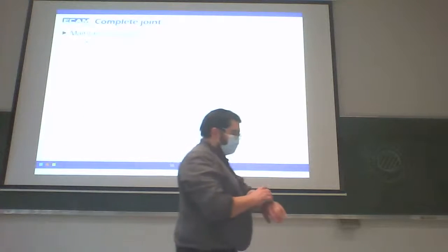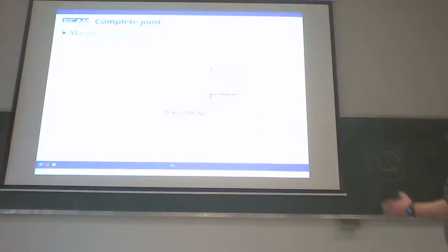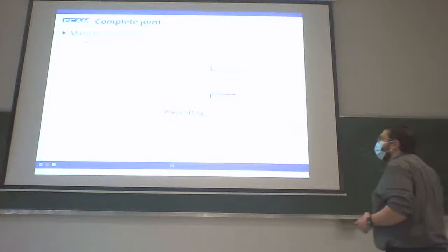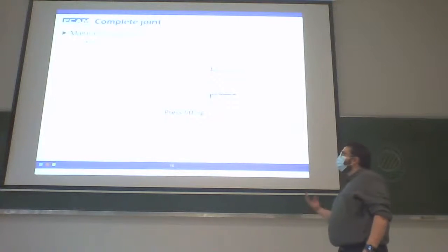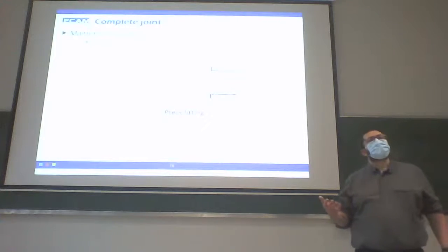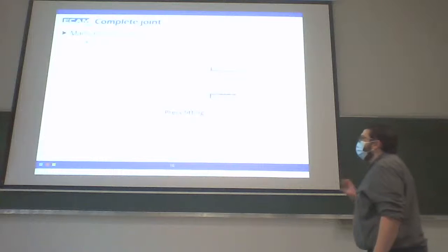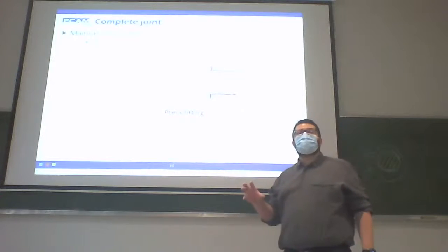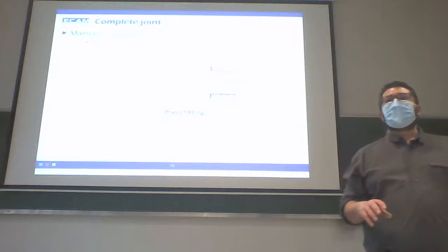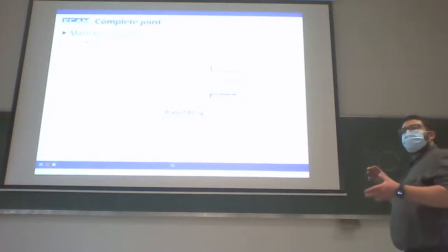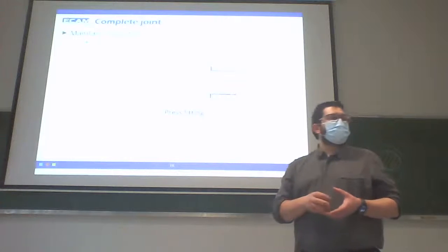Just like this, you have a bore with a diameter D1, part 1, and a shaft, part 2, with a diameter D2. The diameter of the shaft is bigger than the diameter of the bore. We'll exert an important effort to put part 2 inside part 1.